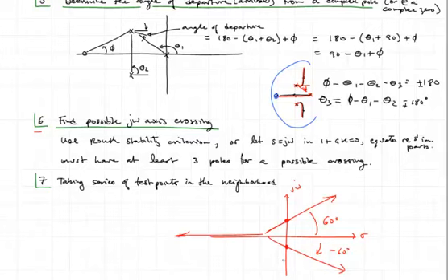At that point those two poles will be purely imaginary. For anything beyond that, like a k value greater than that, those complex conjugate poles would have positive real parts and the system would be unstable. So we want to find where those j omega crossings are.